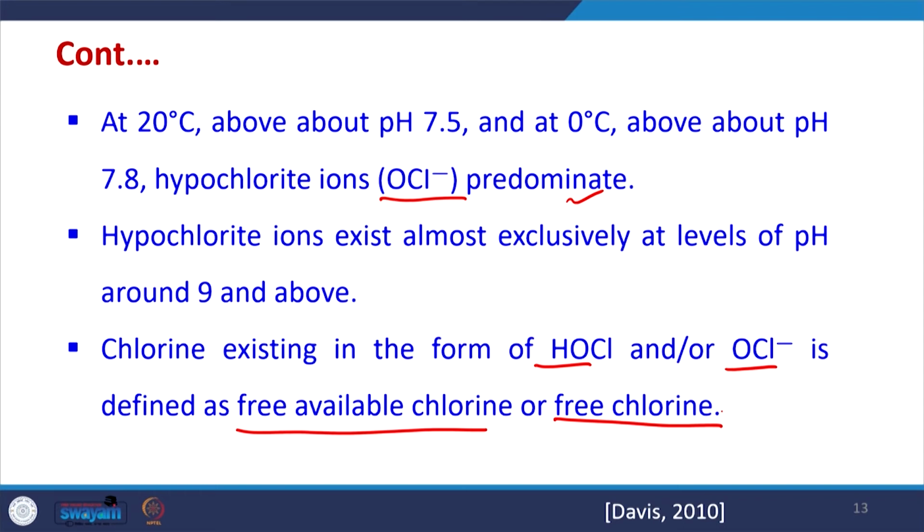So, we always want to know how much free chlorine is available. Also the HOCl and OCl minus have different reactivity or oxidizing potential. Depending upon their potential they are able to disinfect the pathogens which are present in the water.